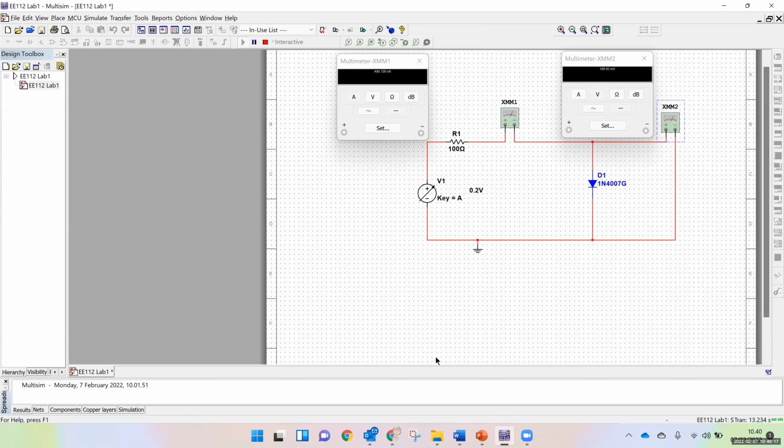Yes, Arish. Miss, in the right multimeter, we choose the voltage? Yes, this is the voltage across the diode. When you connect the multimeter in parallel, it will always give you voltage, so you have to choose V from here. If you choose A, it will give you a wrong result because this is a voltmeter. I need voltage. So this is important. From here you will check A.